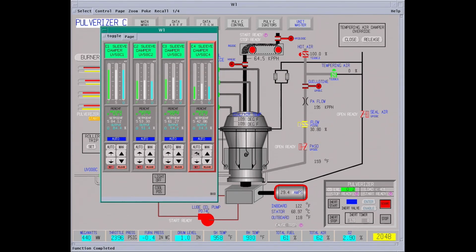These take a little bit to move. I'm glad we can use buttons and control them all. Like after purge, you can bring them all back to light off. When you purge, you have to open the dampers up pretty far to blow any non-burn or any combustible gases out of the furnace. This definitely will change the fire. I'm running a little bit higher on the outside edges.